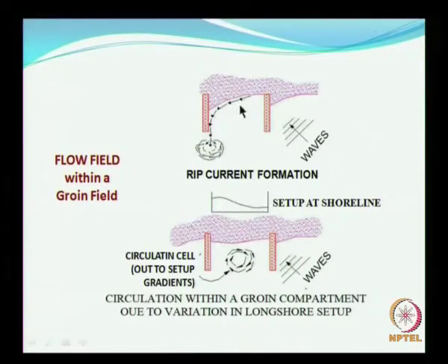That is obvious because there is no obstruction, right. So you see that this is where it will be quite strong. The rip currents are expected to be very strong, and its effect is it can remove some of the materials here if it is an impermeable groin. So you have to be very careful in monitoring the groins, because of this power you need continuous monitoring.